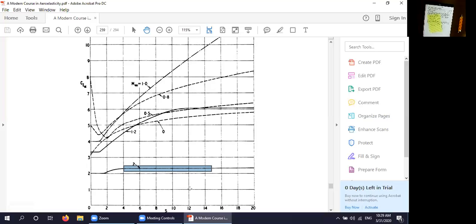Yes, thank you. Okay. So people love piston theory because it's simple and it actually gives you the physically right answer if the Mach number is reasonably high. And for some applications, even at Mach 2, that would not be a bad approximation. But clearly, as you get down to the lower Mach numbers, piston theory tells you something interesting at very short times, but after that, unfortunately, it requires a much more elaborate model than piston theory.